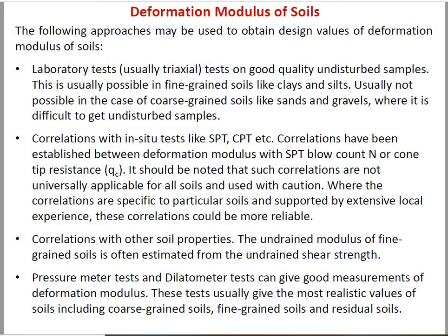Another correlation which you can take, and which I already explained, is the UCC test. If you take very soft saturated clays, there is no need for confinement for such kind of soil, so you apply the UCC test. From the UCC test you get the unconfined compressive strength, and you divide it by 2 to get the undrained shear strength. You know how the UCC test is performed and what the results are, because I have already given a video on this particular test. It's an elementary test.